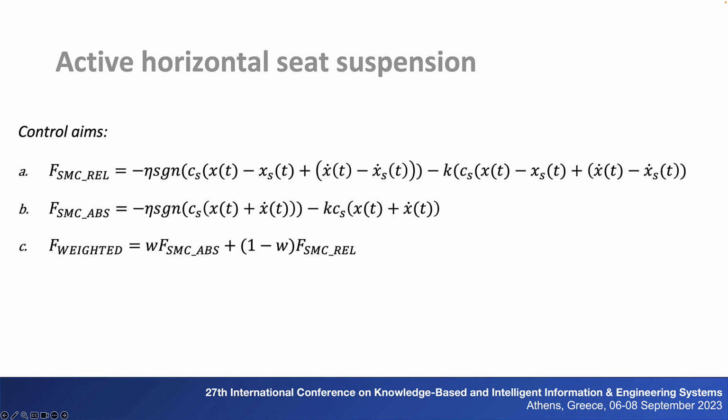In the first case we want the suspended body to follow the input vibration signal. In the second one the control strategy assumes that oscillations of the suspended body should be attenuated around its equilibrium position as much as possible. The third case of control strategy is a compromise between the previous two cases. It is necessary to introduce a weighting factor that would be responsible for combining the active forces, in order to obtain high efficiency of the vibration reduction and satisfying stabilization of the suspension system, simultaneously.